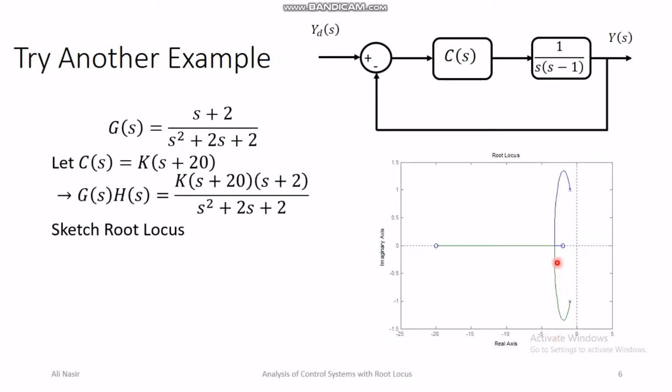So both the poles break in at -3, which means that although we can drag one of the poles to -20, which is good, we cannot drag both of the poles to -20. And we want to drag both of the poles to -20, because one of the poles we were able to drag to -infinity using the proportional controller as well.